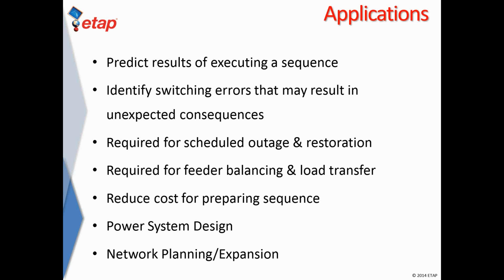So it is also a tool that can be used to verify any existing switching procedure that you may have already in place. Perhaps your switching procedure hasn't been verified and validated in many years. Perhaps your system has changed and you're constantly trying to keep up and validate with all these switching sequences. The switching sequence manager, SSM in ETAP, is the tool that was designed just for that.